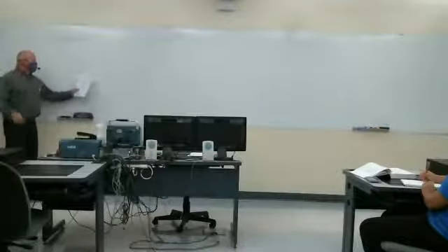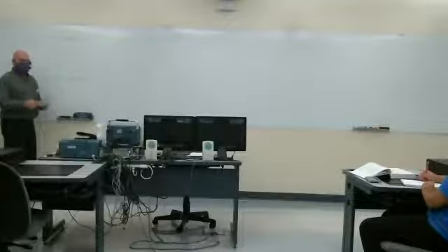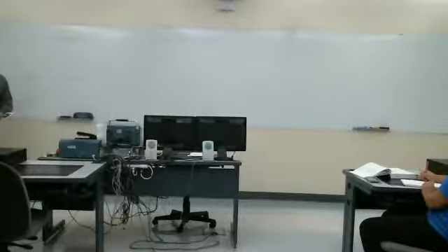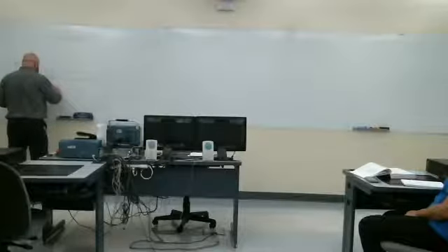Now, if the system is linear, and this circuit is linear, then we can find the response to a sum of inputs. That response is going to be equal to the sum of the outputs for the individual inputs. In circuits, you call that superposition.